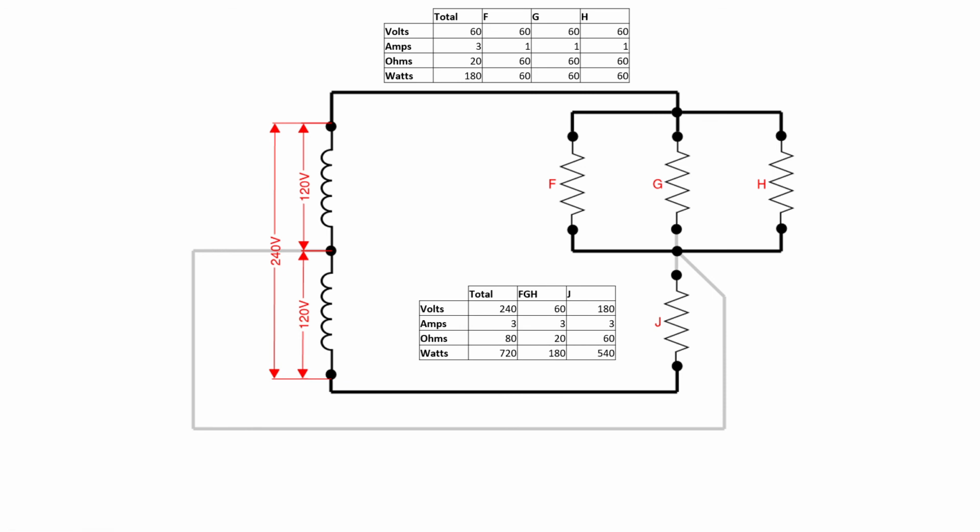So again, that's a very complicated calculation. You can see why everything kind of goes crazy. I mean, this lamp gets 180 volts applied. These only get 60 volts applied. So these are now halfway dimmed. This one just blew up. And in fact, if these were incandescent lamps, we just blew this up. Now the circuit's open. Now nothing works. So you can just see the amount of trouble that's going to cause. But that's a very complicated calculation.